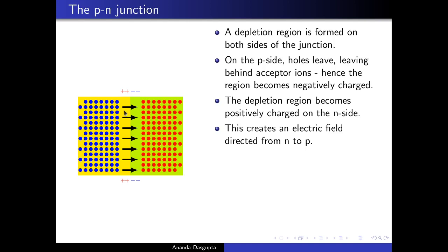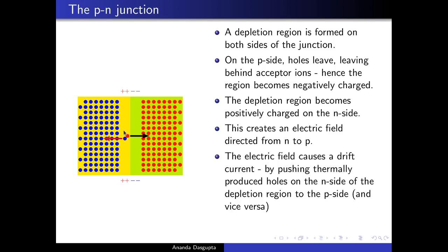Suppose an electron hole pair is formed in the depletion region, let's say on the n-side, just to be specific. So the hole is pushed by the electric field to the right into the p side. So the hole is made to cross over. Electron, on the other hand, is pulled in the opposite direction, same electric field, but the negatively charged particle. So electron gets pulled back. So both of these go out of the depletion region because of the electric field.